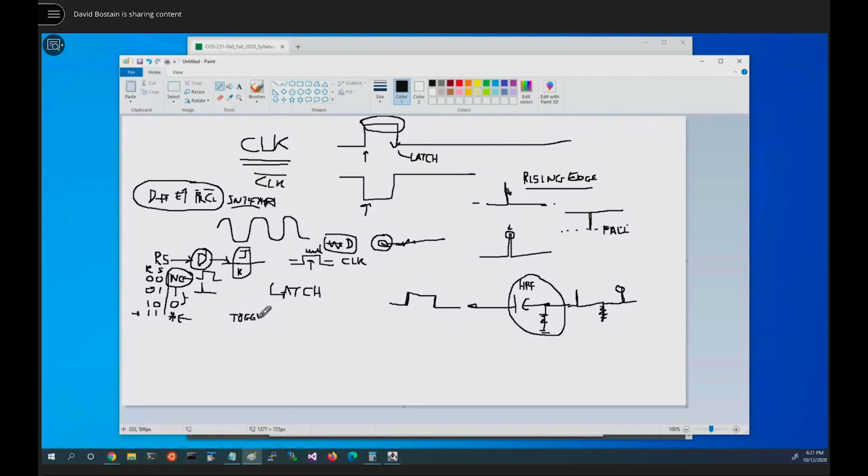So on every clock it receives, and for JKs we want the clocks to be edge triggered, we want to see Q change to whatever Q wasn't. So Q and not Q will flip-flop back and forth. Part of the name flip-flop comes from that. But if it had a level clock, as this did or as the RS might have, we would call it a latch.